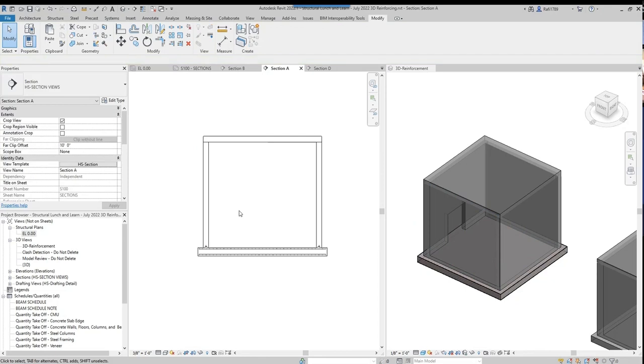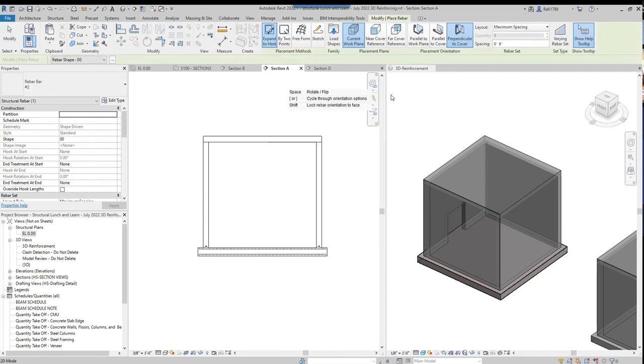And some of you might do this a little bit different than I do, but this is kind of what I typically do. So I'm just going to go rebar, and I'm going to keep my rebar shape 0. I'm going to leave it as expanded to expand to host, and we'll look at that by 2 points when we do the dowels and some splices. In theory, you could still do freeform rebar. You could, in theory, do area reinforcement. I'm not a big fan of area reinforcement in walls. I know some of you will do it.